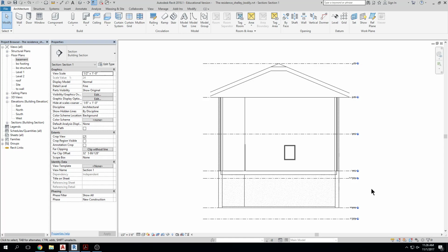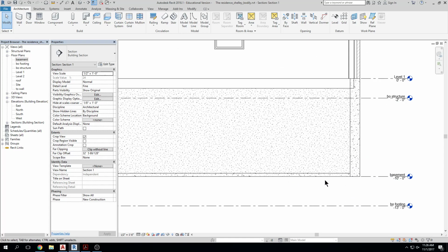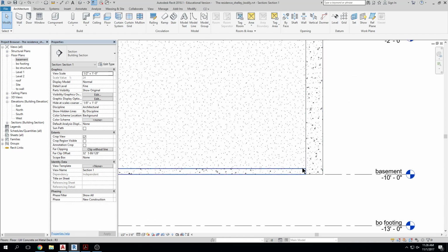Okay, there's kind of a balance between, do I actually create a level that's called top of basement slab? Or, in this case, is it good practice just to say, oh, I'm going to offset my slab up 4 inches, right? You don't want to get in the habit of defining objects in Revit and not defining them as they should be and just using an offset, right? You want to define them appropriately and correctly as much as possible. But in this case, it kind of makes sense. It's one object, and there's not going to be really anything else that you're going to have to worry about with this. It's okay to offset it, right? You don't need to create a new level for top of slab, okay, essentially.